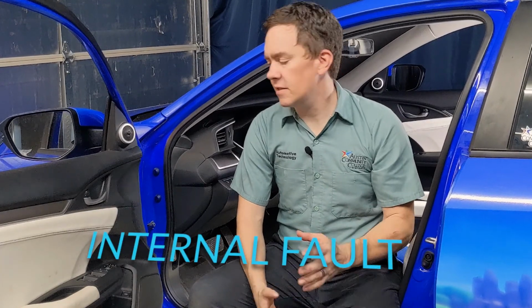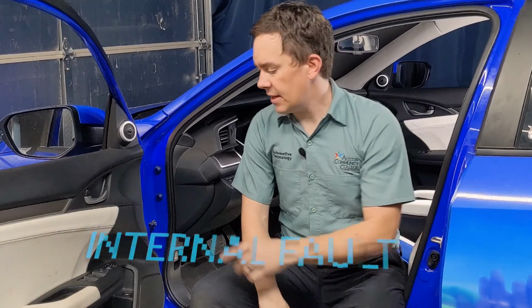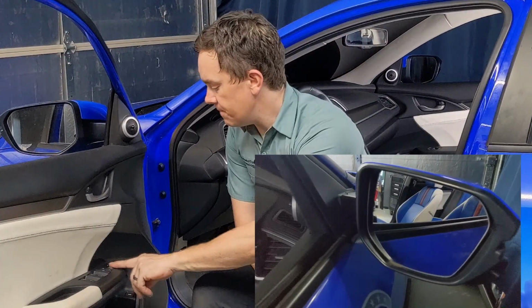Next, let's look at a different fault scenario. In this instance, my powers, grounds, and data lines are all working correctly, but I've got an internal fault on the passenger window switch. My passenger window works fine from both the passenger and the driver switch, but the passenger mirror, that's a different story.